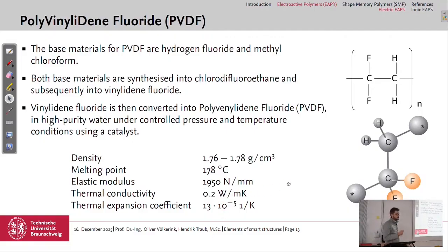And compared to other structural materials we use, like GFRP, CFRP, aluminium, the elastic modulus is really low, about 2 gigapascals. So here is a square missing, I've seen, so it's Newton per square millimeter. And therefore, I would say PVDF is more functional than a multifunctional material.